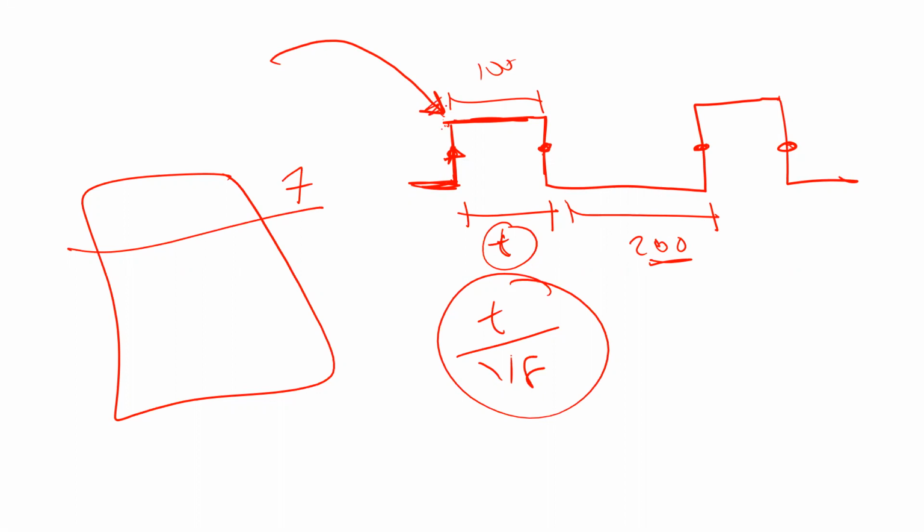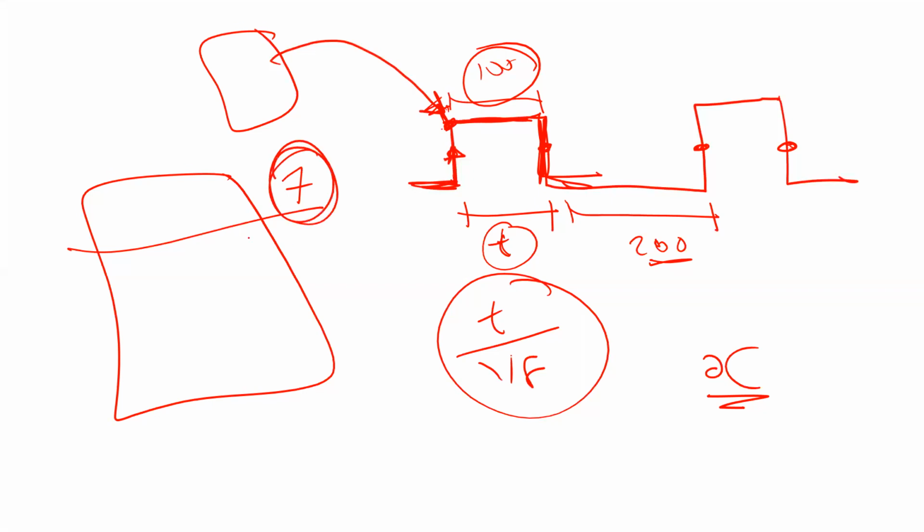And then once I come here, I'm going to tell the output compare, please toggle the pin after 100 counts. Okay, that's it. You have to say that in the subroutine, and everything is going to be done automatically. So if the count now is 7, output compare is going to wait until 107, after 100 counts, to do this toggle.